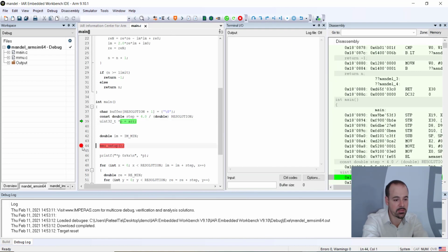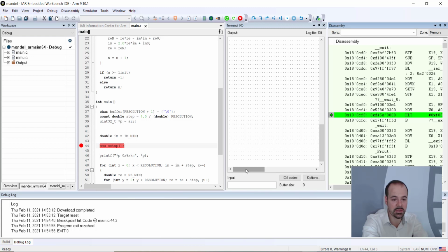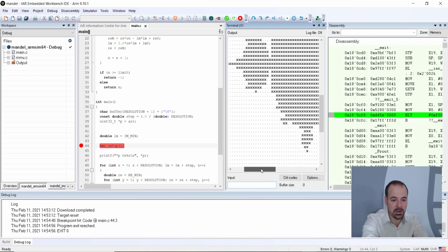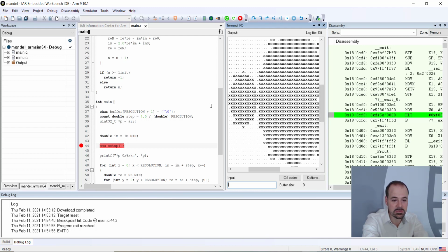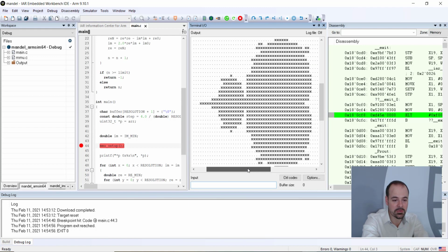And I can, of course, set breakpoints at any point. If I run the application, it can stop here. This breakpoint can be turned into a complex breakpoint where you put a condition if a variable has a specific value or higher. That's also a possibility. But if I leave this application running for now here, it will print some information for me. And for your curiosity, I'm mainly printing here actually almond. That's of course some of the fun part of the demo here, but you can do anything on this application. It's up to you. So as you can see, very easy to use.